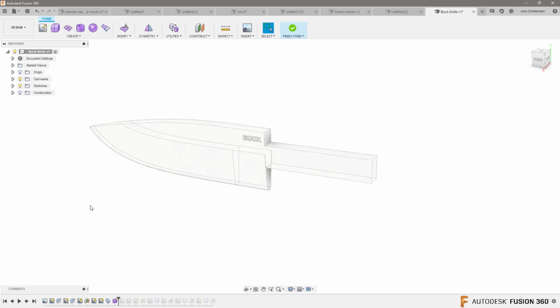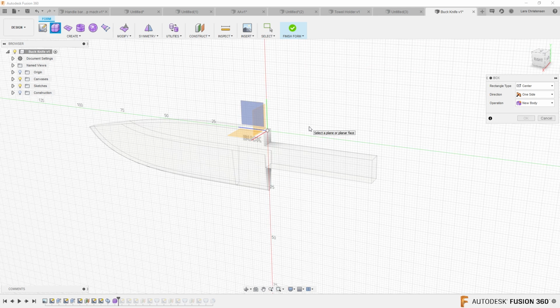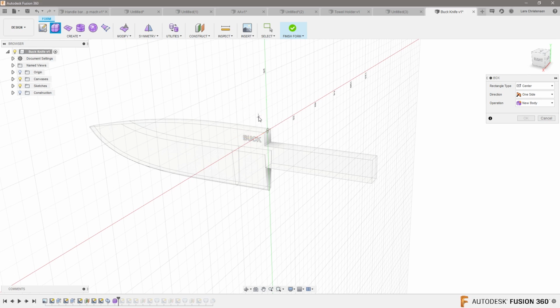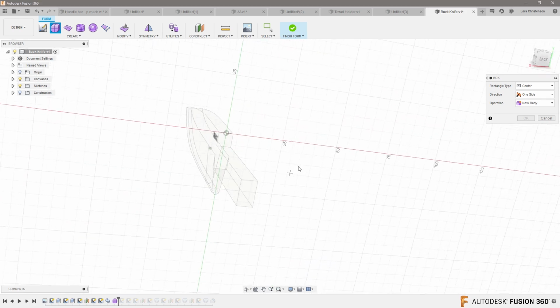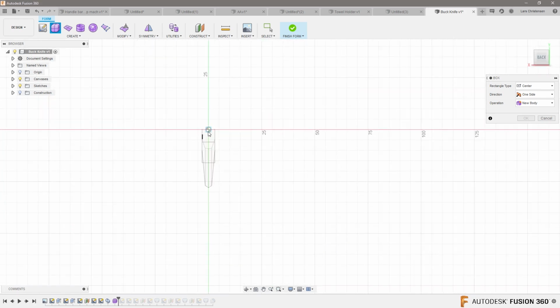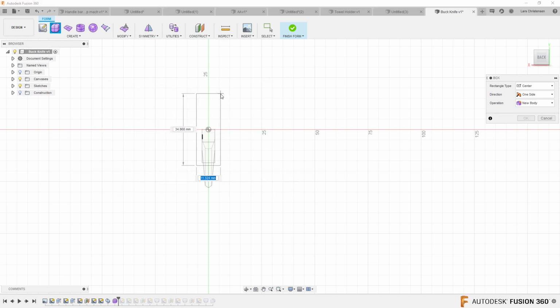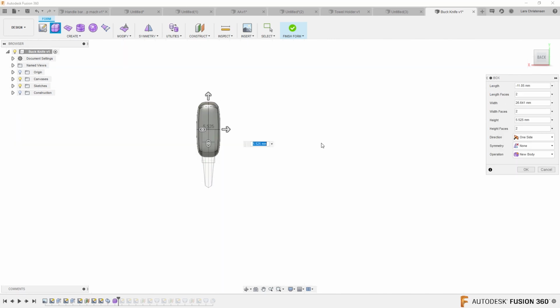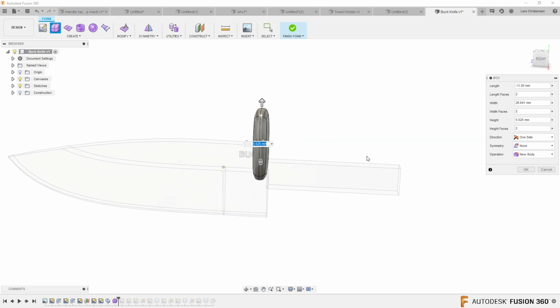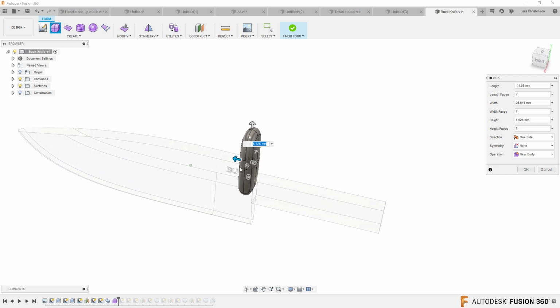I'm going to jump into the sculpt environment. I'm going to use this perimeter box here, and I'm actually just going to kind of draw. It doesn't matter really what plane you're drawing on. Actually, this is kind of crazy. I'm going to draw up something that I think is going to be a handle looking like this. And without exiting out of this, you can actually make some changes over here, which is kind of nice.